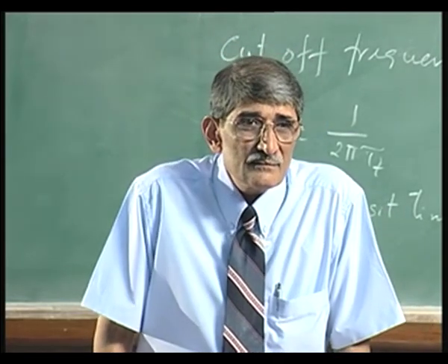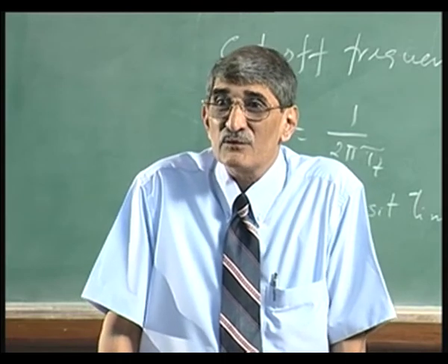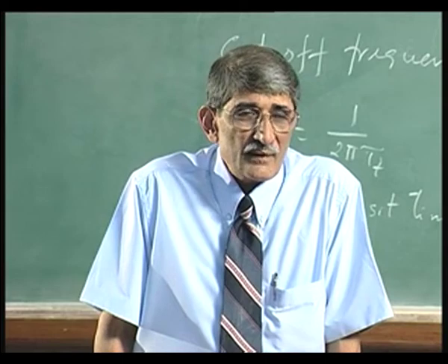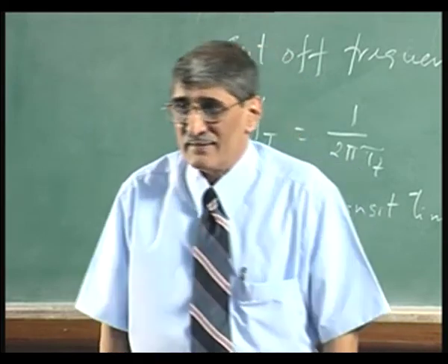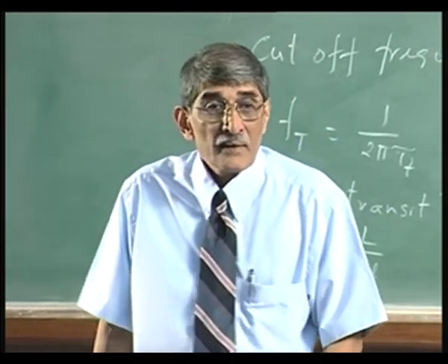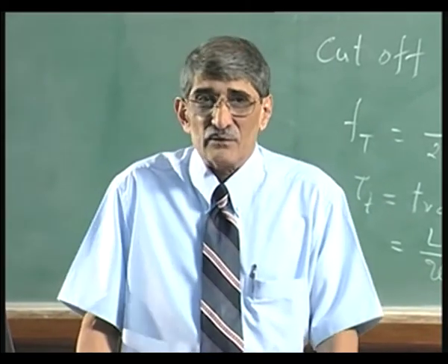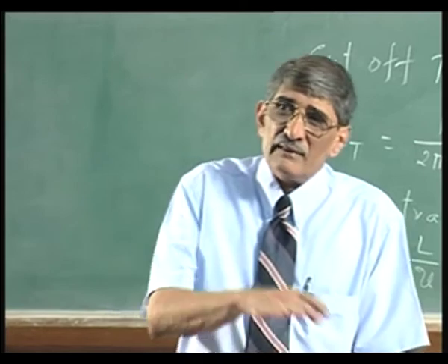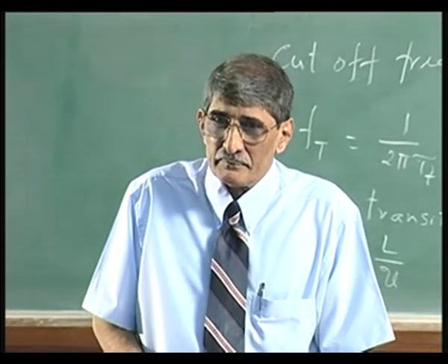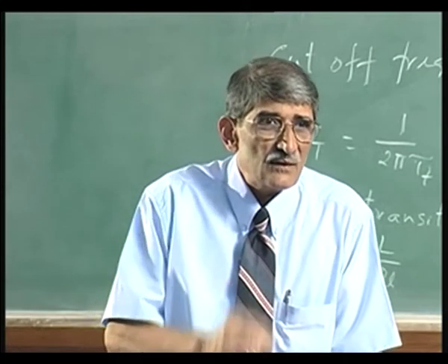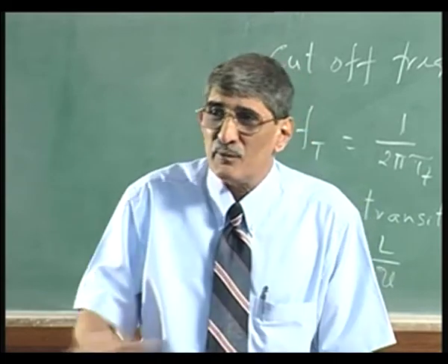In silicon also you must worry about the doping, because threshold voltage depends upon twice phi f. Threshold voltage depends on doping in substrate in addition to oxide thickness. So, oxide thickness uniformity and doping in the substrate both control threshold voltage. Over a 12-inch wafer you need that uniformity. Okay, this is one of the problems people face when you go to thinner and thinner oxides, to get perfectly uniform over the entire wafer.